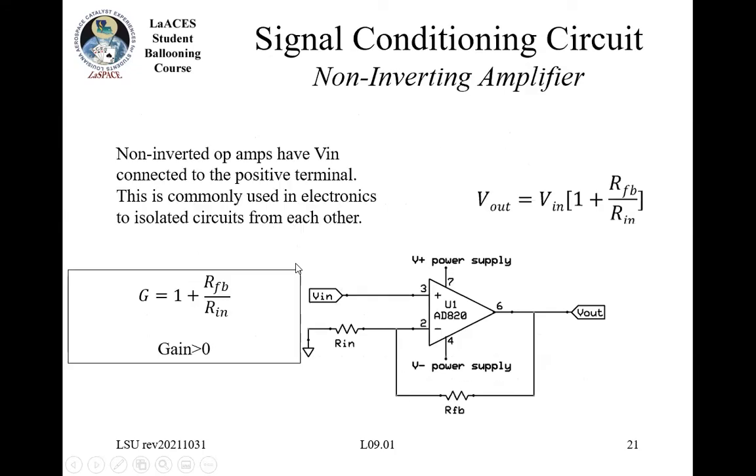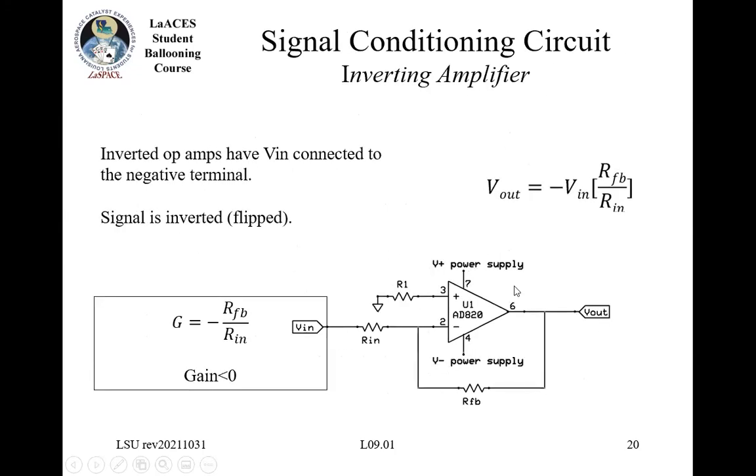With the inverting amplifiers, you can now see why you would often have a positive voltage and a negative voltage, like plus 12 volts, minus 12 volts, because otherwise, when this gets inverted, it's just going to get set to the minimum value, which would be 0 if this negative supply pin was connected to ground.